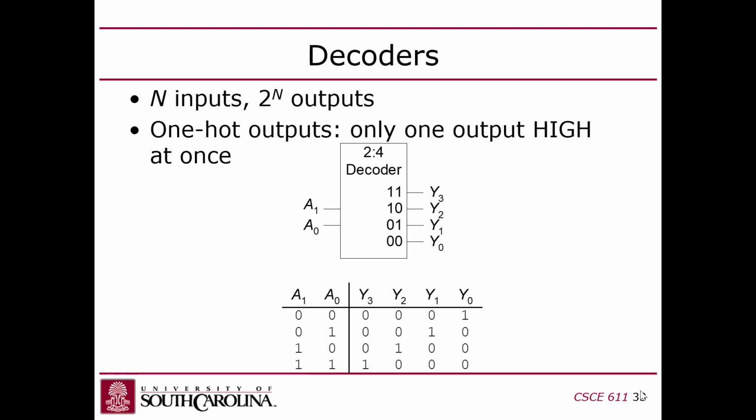So in lab 1, we're going to ask you to create a decoder, but we're going to do a 7-segment decoder, a little different, and I think you built one of these in 211. The idea is you take a 4-bit binary value that could be any of its 16 values, 0 to 15, and then decode those to not a 16-bit output, but a 7-bit output for a 7-segment display, right? So it's still a decoder in the sense that a smaller number of inputs are being converted to a larger number of outputs, right? You guys with me?